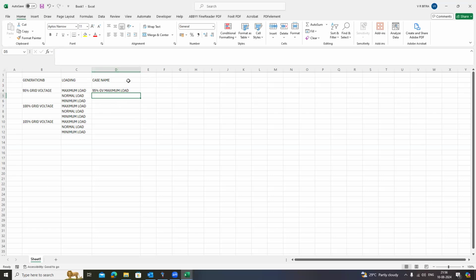And obviously that will be the maximum current, because the voltage is less so I am still trying to draw more power. So I is inversely proportional to voltage, because the loads, whatever I consider, are constant power loads. So your power will be constant. That means if the voltage gets reduced, automatically the current will increase. So this will give you the maximum loading.